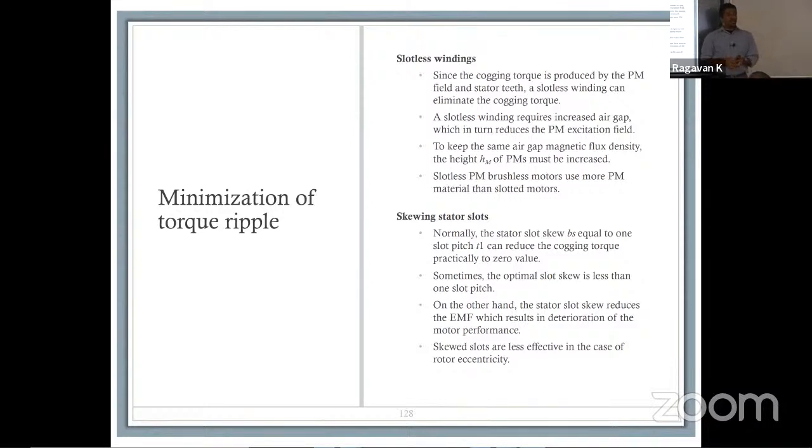So you have to find a good way, because if you remember how we talked about specifically creating mechanisms for stacking them. So now if you want to skew them, you might possibly be looking at creating notches that are staggered. Here's the challenge of whenever you have anything that's staggered. Can anybody tell me what that challenge could be? What is the one possible issue with having laminations that are staggered, or essentially where your notch is, let's say, moving all the way from the right to left?